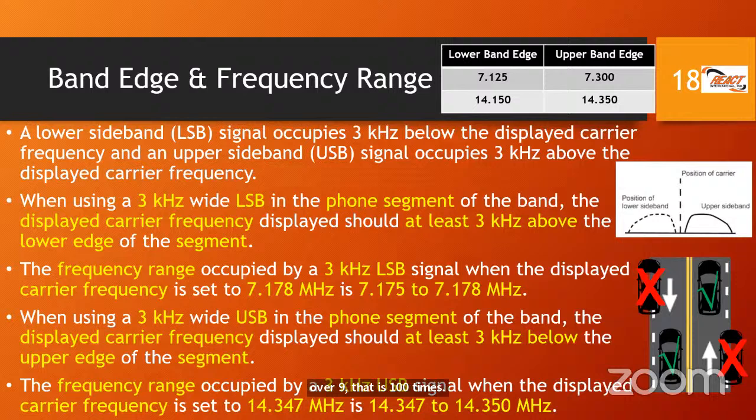Right, so we have talked about single sideband before, right? And on your screen here, we have a little representation of what single sideband is. Remember, we have our carrier signal, and then when we modulate our signal in amplitude modulation, you have an upper sideband and a lower sideband that's generated. We also said for sideband operation, what we do is remove the carrier and one of the sidebands, and we are left with one sideband. So for example, we are left with the upper sideband. So this is just a little revision. If you have any doubts about that, you could look back at the previous material.